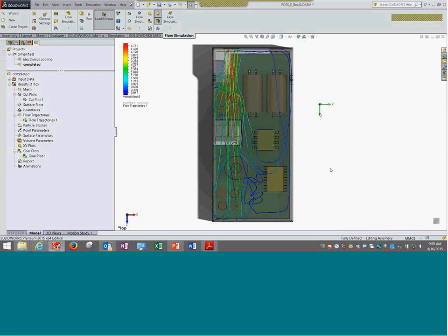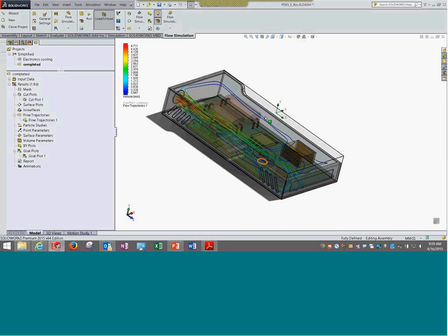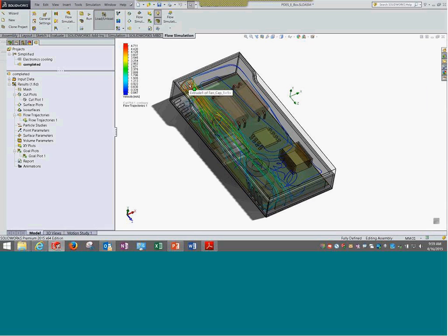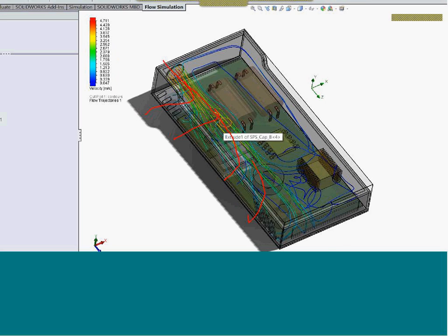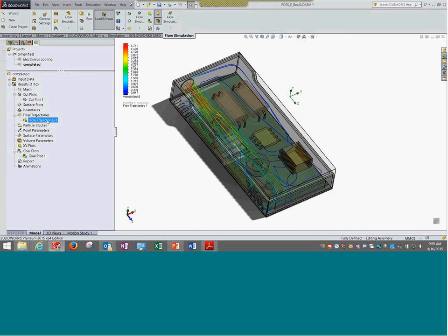Sorry, I mean, this is not a good design. Since we have holes all around here, if you observe this closely, air is coming in from here, and it is just going out probably something like this, most of the air. Where heat is getting generated somewhere down here, right? With probably the capacitors as well, which are comparatively big, and the heat is actually dissipated from this particular heat sink, and we are not taking it out of the system. So obviously, this can also be seen as an example to improve your design.